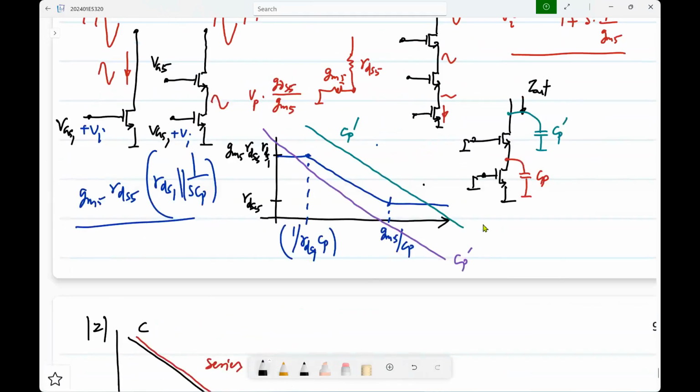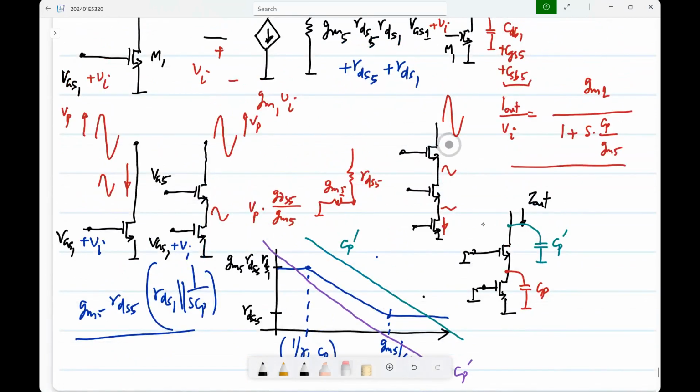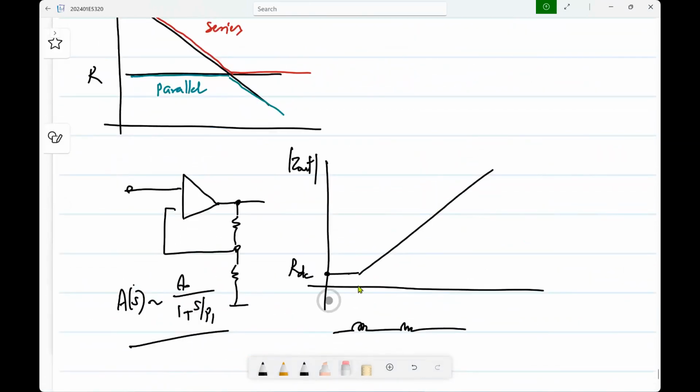So the other one here, we wanted very high output impedance, but it becomes lower. Basically, at high frequencies, you get screwed. That's the moral of the story, right? Because the loop gain always falls, and something that should be resistive becomes capacitive, so the impedance drops. Okay. Similarly, here, at high frequencies, it becomes inductive. Okay.